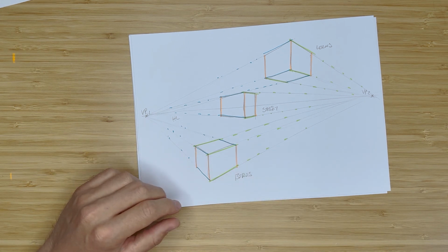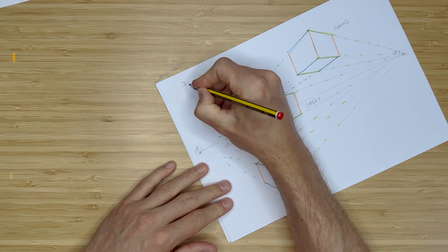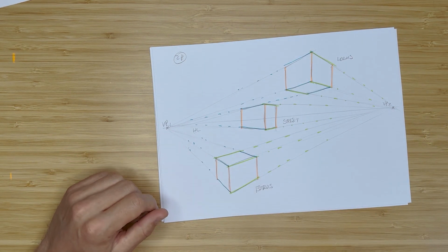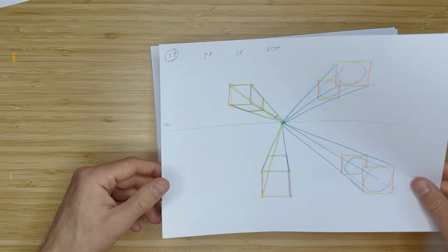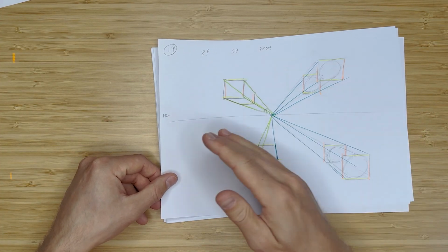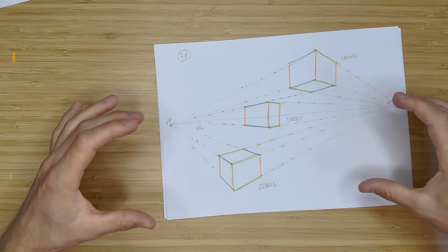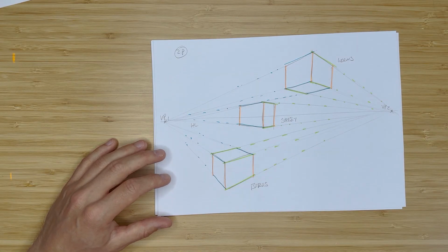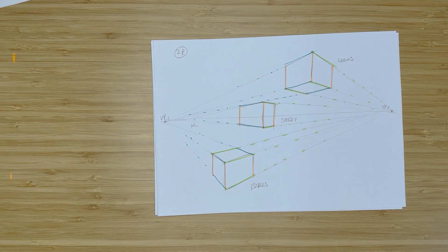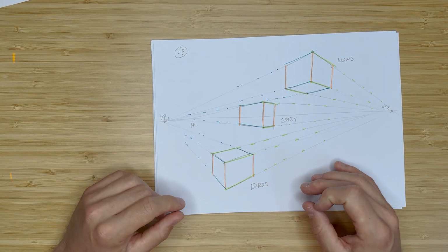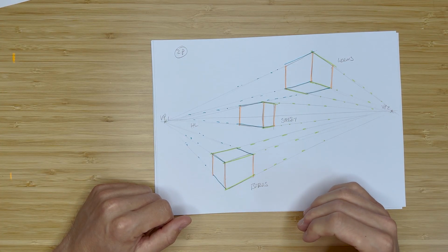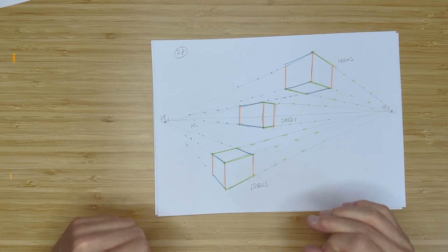So that is our 2-point perspective as well. Okay, so we've got 1 point and 2 points. You can kind of start to see the trend. 1 point has a single vanishing point on the horizon line. 2 point has 2 vanishing points on the horizon line. Have a go at sketching some different shapes, different size cubes and cuboids for this, and we will have a look at 3 point and fisheye in the next video.